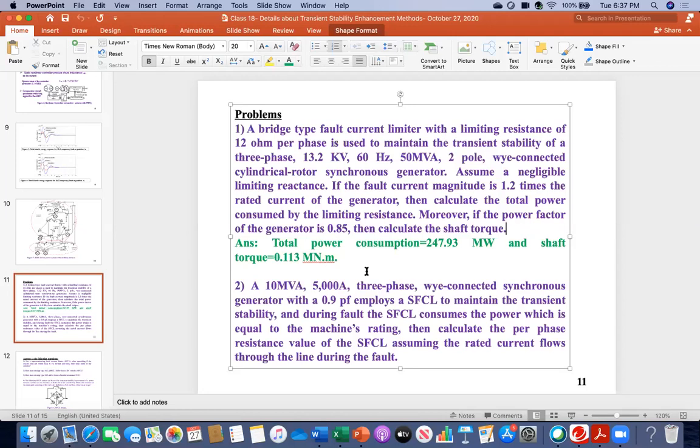So Amani, are you doing torque equal to power over omega in radian per second? Yes, I got 376.8 radian per second. That's right. And then power will be that 50 MVA multiplied by the power factor. I got 58.82 for that. Okay. I expressed the result in green color, I have written 0.1 mega Newton meter. First you see Newton meter and then you can convert into mega. So you can check that it is matching.